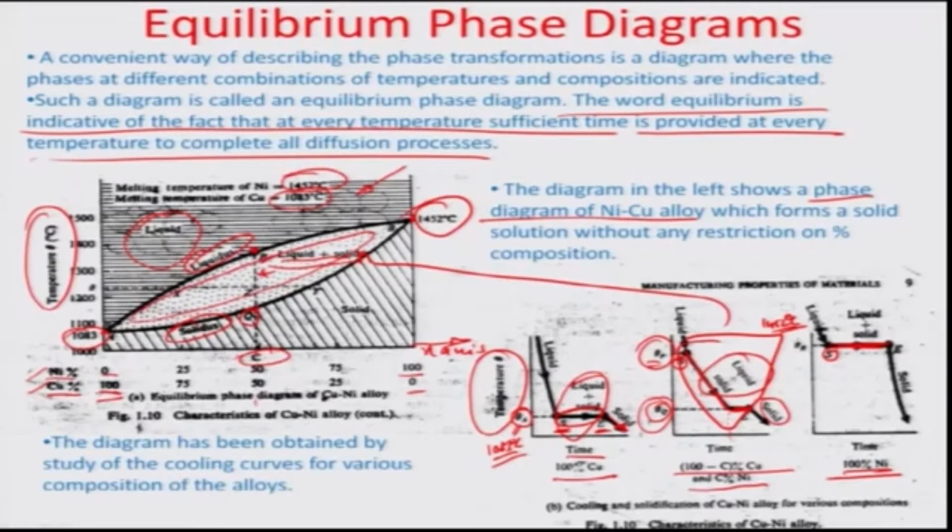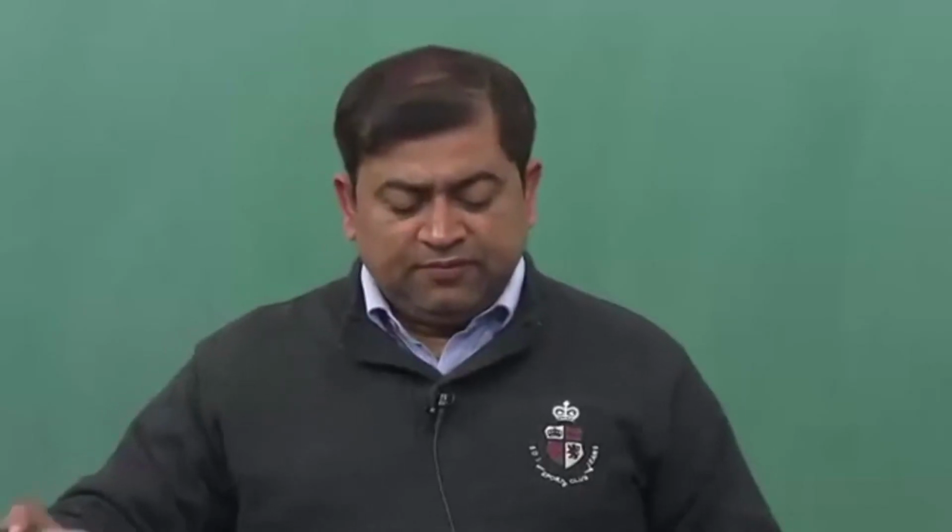So this PQ here is really the temperature difference between this theta p and theta q. Okay, so you can plot that as a function of the concentration, and that brings you the array of such points which would be the liquidus, and the array of such points which would be the solidus, which would lead to the emergence of this curve from this curve right about here. Okay. So that is how equilibrium phase diagrams are plotted. Let us look at the interpretation.